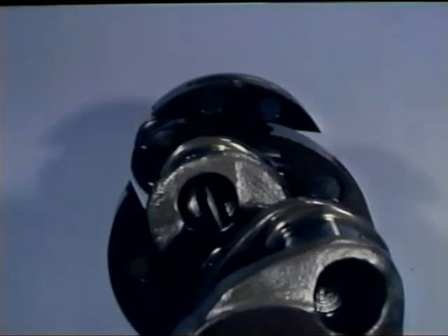The crankshaft for a 6-cylinder horizontally opposed engine has its throws forged so no 2 are in line. This means that a throw brings its piston to top center every 60 degrees of crankshaft rotation. The firing impulses occur 60 degrees apart from each other.